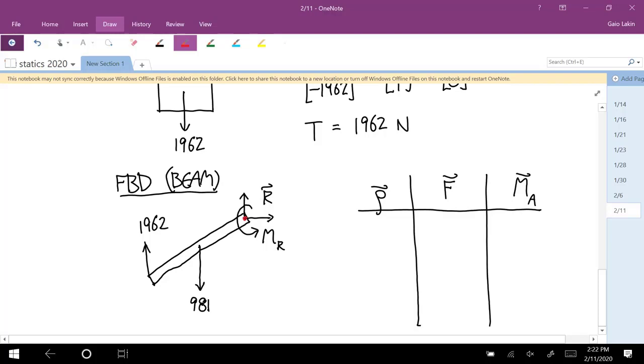That's the other place where statics makes you a little sloppy, because in dynamics, you only have a couple of choices about where your about point can be. In statics, it can be anywhere. Okay, so the red is the about point, and let's just go through all these loads and fill out a row for each one. So first I'll deal with that reaction force R. The row vector is the vector from the about point to where the force is applied. So what's that in this case? Yep. So 0, 0, 0.